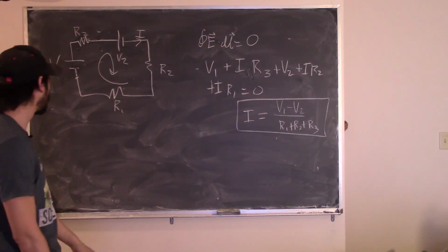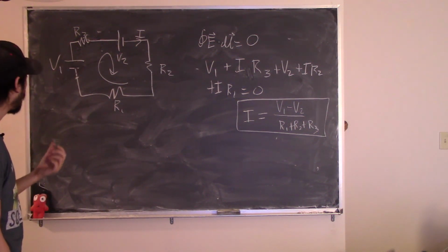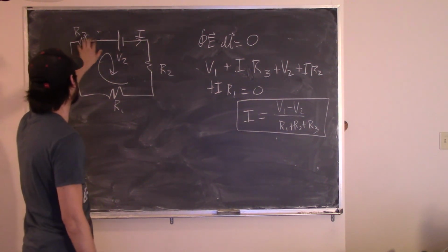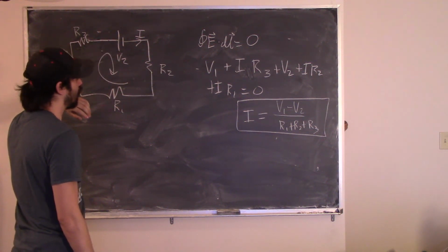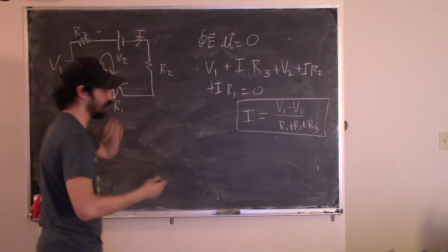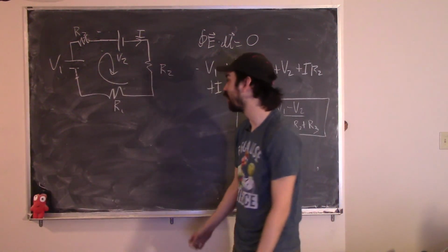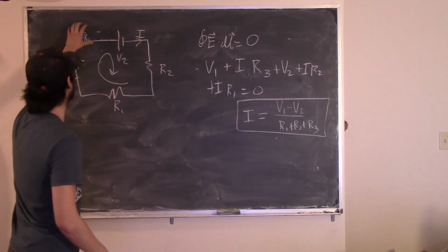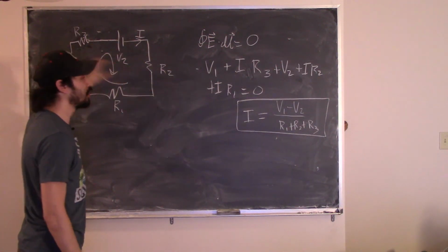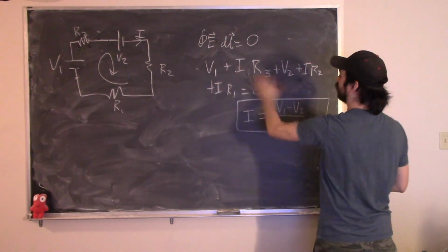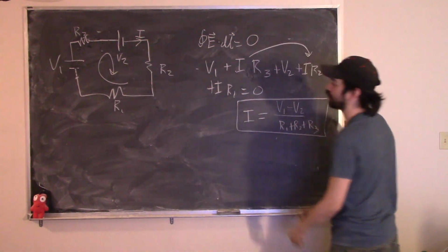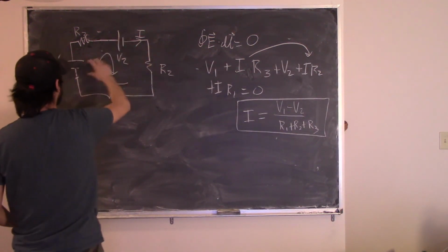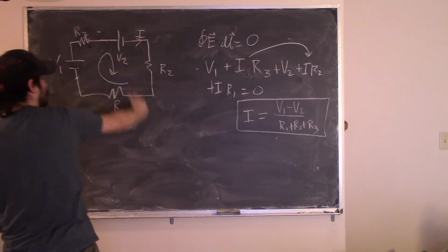But the interesting thing about this, because you ask if I have to worry if I put an R between the two batteries. On a theoretical level, and I mean this in terms of the theoretical physics and the math, not just a conceptual level, there's no difference between having this R3 here and having it over here. Because this equation is exactly the same whether I have this term over here or over here. Which means that, as long as I don't flip the orientation of any of these things, I can put any one of these things in whatever order I want.